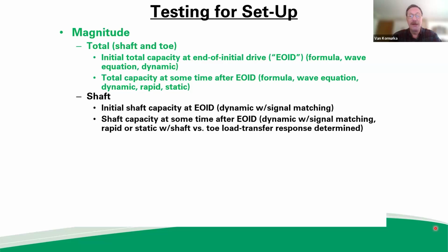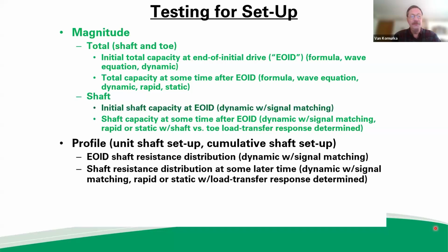And then again, at some time after driving, you have to separate shaft from toe, which during restrike, that is, separate shaft from toe resistance, which you can do with dynamic monitoring or with a static load test if you instrument it for load transfer response. And what that means is install strain gauges so that you can separate the shaft from the toe, at least one strain gauge near the toe.